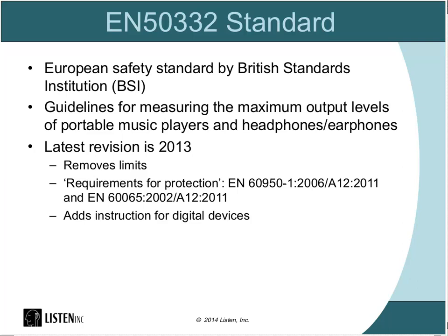So the EN50332 standard itself is just a measurement standard. It just tells you how to perform the measurements and what data to collect. These other standards and other places, depending on what countries you're working with, will have their own guidelines over what you then need to do with your product to make sure it is compliant. So in these sequences, don't be surprised when you don't see a pass-fail at the end. We are not applying the limits from any of these other standards. That's up to you to decide what you want to actually test your devices to.